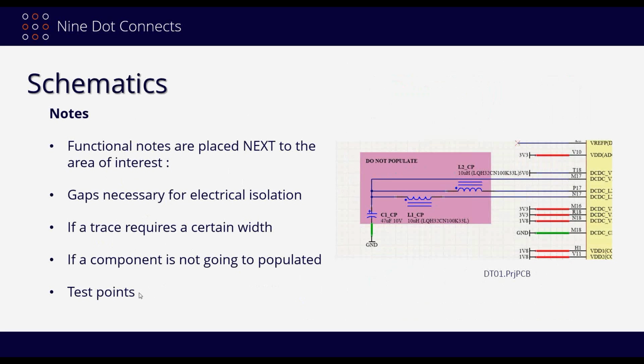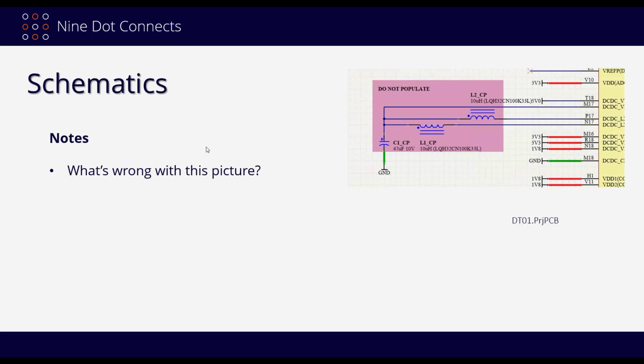What are you trying to test on that test point if it's not obvious? You know, sometimes you just put on a wire, okay, I've got this test point, that's great. But if that test point's there for something else, they say, what are you really testing with this? Yes, I can see that wire. I see its net label. What am I trying to get off of this thing? Am I trying to get off a specific clock? Am I trying to see if the reset is going to work a certain way? Is there a certain signal that I expect to have a certain duty cycle on it? Whatever it is, you want to make sure that the test point is there and explained if it's not obvious.